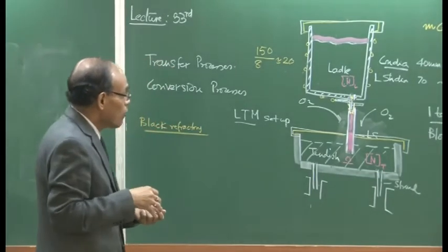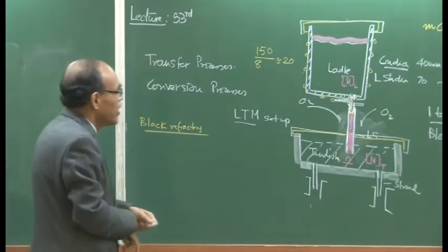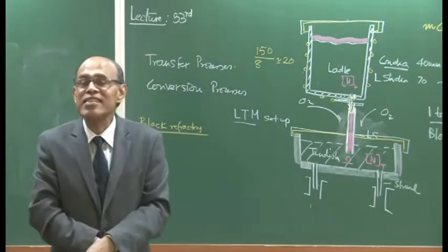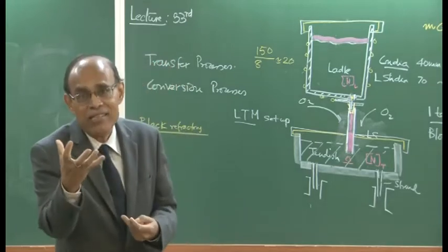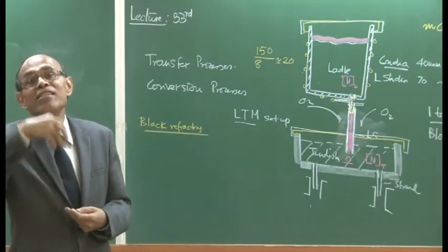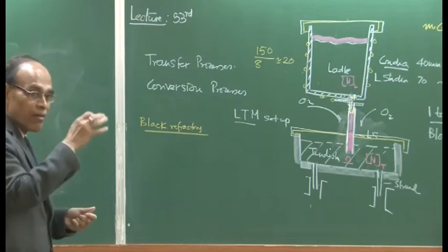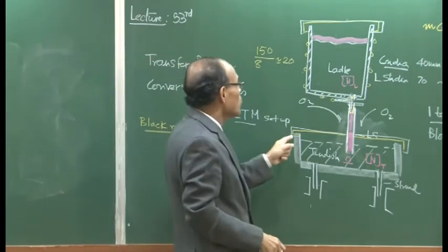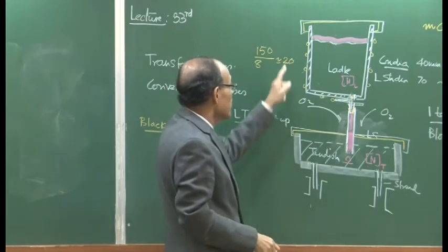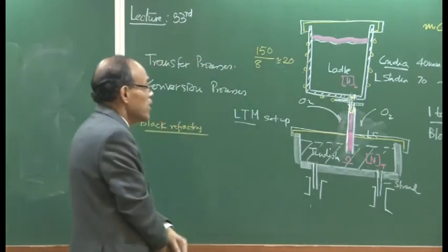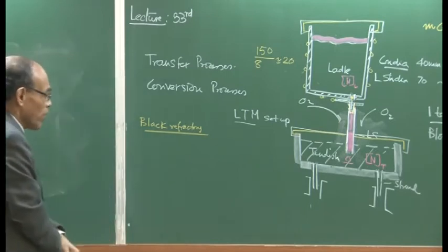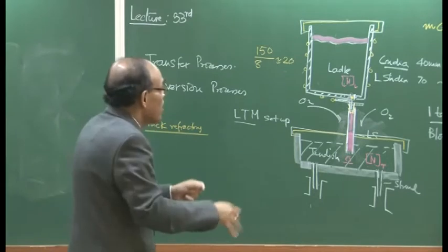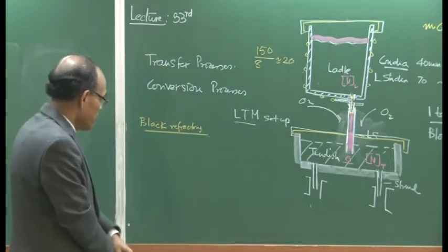So, this will have a direct impact on electricity consumption, on carbon footprint, etc. There is quite a bit of effort in the steel industries now to harness the heat which otherwise is being lost to the environment following the melting operations of steel, and more and more tundish covers, ladle covers, etc. have been used in order to minimize heat losses, so that the power consumption in electric arc furnace can be smaller. The processing time thus will also be smaller.